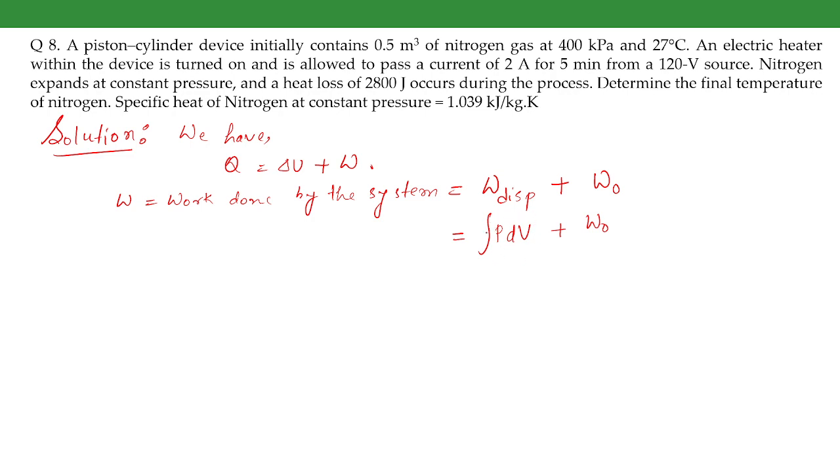So this term is the pressure that is causing the change in the volume. We are considering it at an infinitesimally small control volume. We are making an infinitesimally small change in the volume, that is dv, and the pressure that is causing that infinitesimally small change, and we are integrating it throughout the entire change in the volume. Okay, so in this, writing the displacement work as integration of p dv, if there is any doubt, please ask.